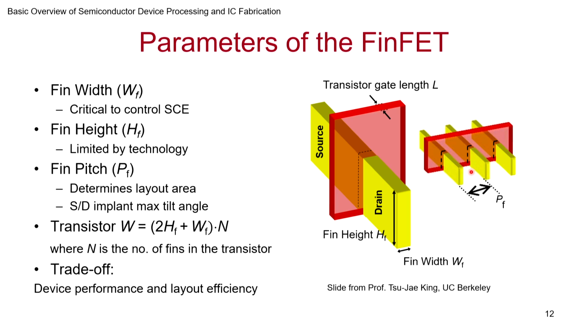So this distance between them is controlled by, and will control, various subsequent process parameters, and maybe even limited by that. One of them, as I said, is, for example, if I want to dope this fin, I have to dope it at an angle from here. So when I'm doping this first fin, the second fin will be shadowing it. So you have to make sure what is allowed and what is practical.